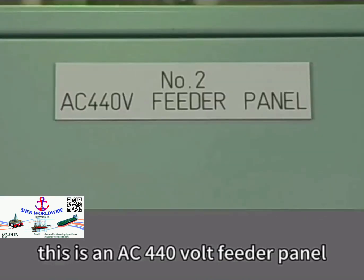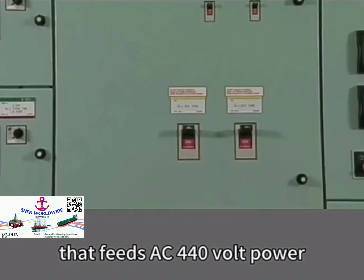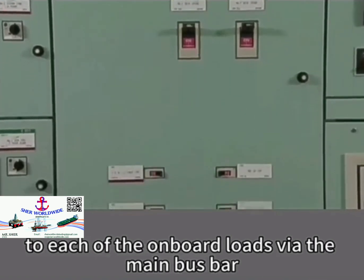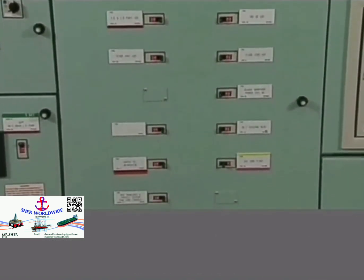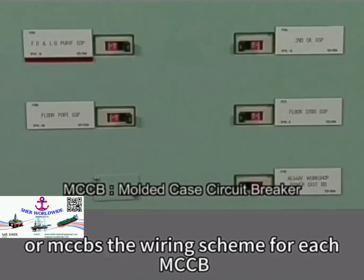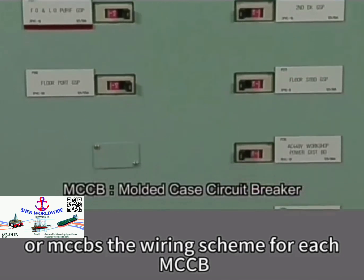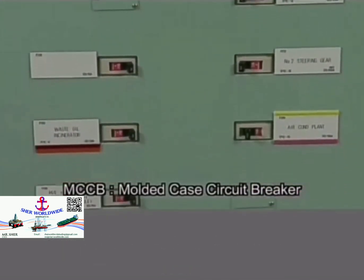This is an AC 440 volt feeder panel that feeds AC 440 volt power to each of the onboard loads via the main bus bar. The feeder panel is equipped with molded case circuit breakers, or MCCBs. The wiring scheme for each MCCB is indicated on its label.